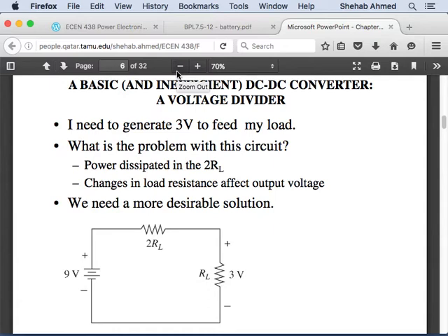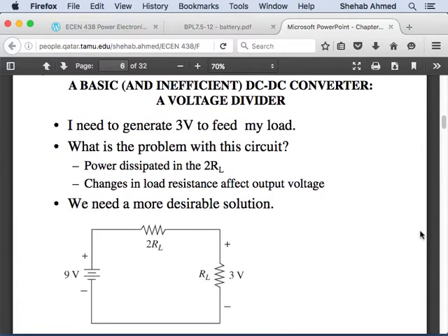So you will have to choose your power devices, your control components, your reactive elements. You put those in there, program it so that you can calculate your metric, and then you choose based on what you want as a metric. If you care about size, you will design it for size. Care about efficiency, you will design it for efficiency. So now I use a more classical approach, following a textbook. So I think it's easier. But hopefully you'll learn as well.